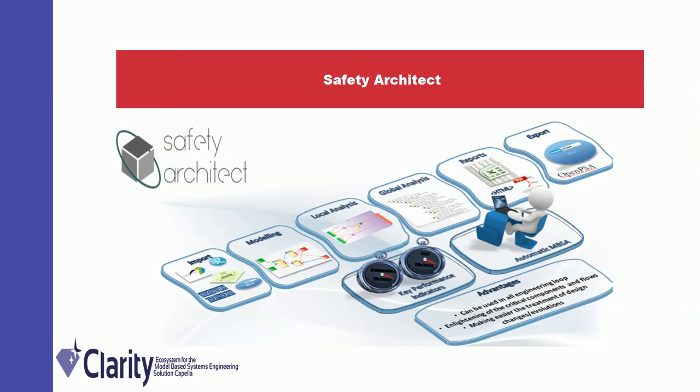Indeed, Safety Architect can import design models from user modeling tools such as System Architect, Rhapsody, Skate System, Papyrus, or Capella tool in order to perform classical safety analysis, namely local failure condition analysis that we call local analysis and automatic generation of fault tree for the identified failure event that we call global analysis.